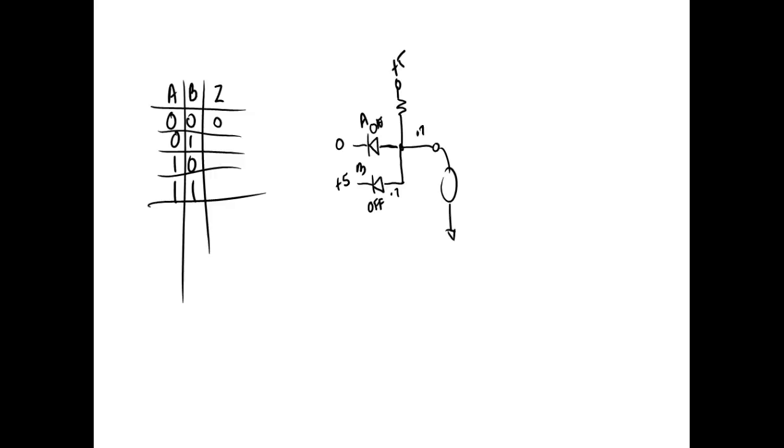It's still the same. It's just that we turn the diodes on. I mean, it's still the cathode has to be negative in respect to the anode, right? As soon as this guy here turns on, the 0.7 of a volt, that puts 0.7 right there. That puts plus 5. Is the cathode negative in respect to the anode? No, it's positive. So what's it going to do? Okay, so what's this going to give me? It's going to give me a 0, right?